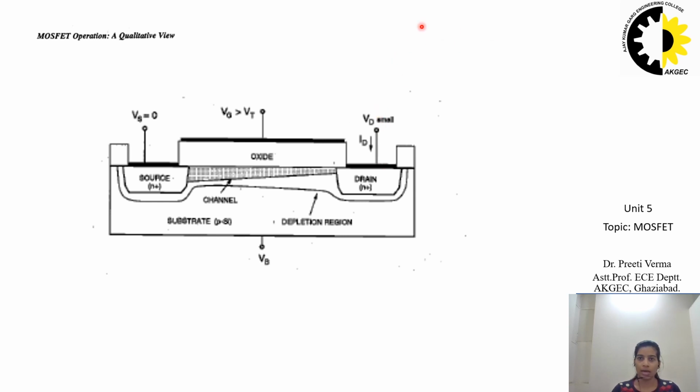If you look at the right half of this circuit, there will be a small difference between Vg and Vd, so a small voltage will be applied to this region and the charge attracted near the interface will be reduced. So the channel will get thinner towards the drain side and the depletion region will get broader towards the drain side.